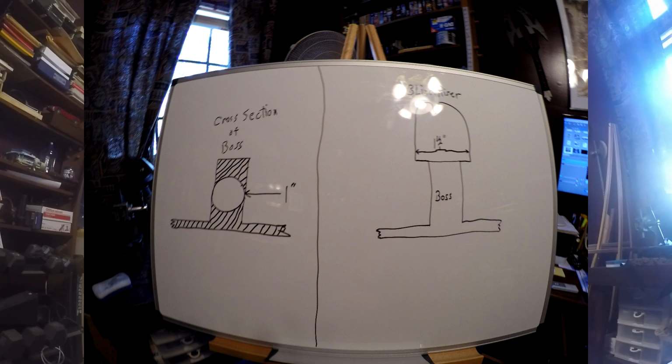You will absolutely have the hottest metal in that riser, and no matter what's happening elsewhere, that riser will stay hotter than the rest of your casting and will feed your casting.